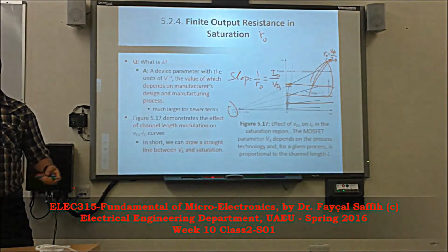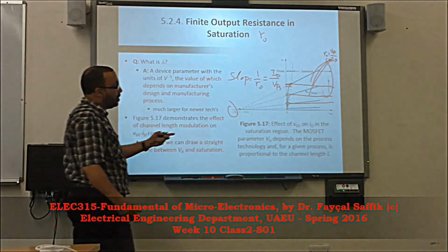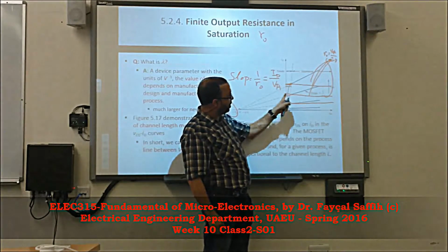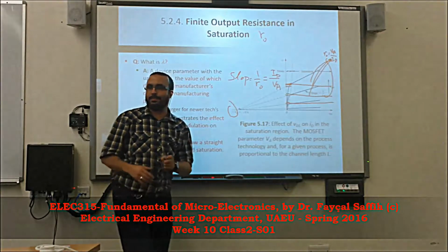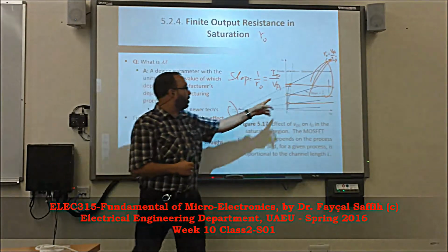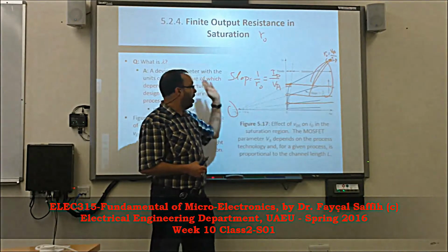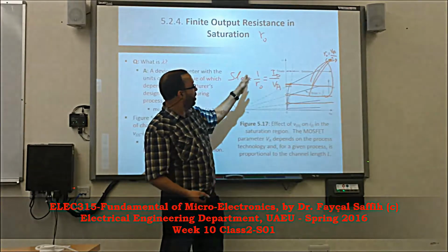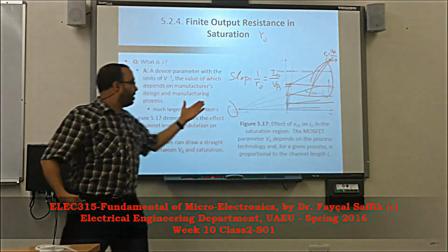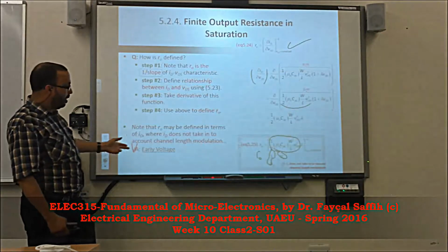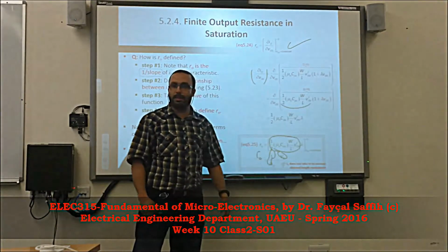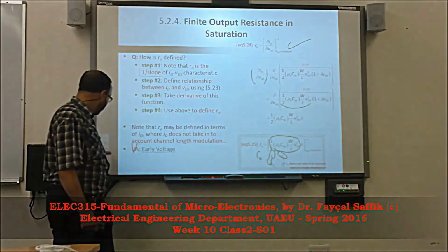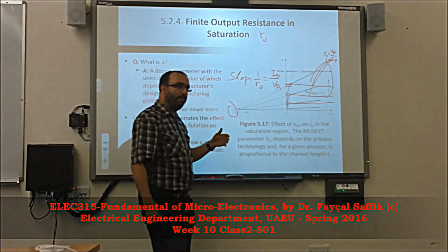That's it, you got it? As simple as that. But it is an approximation, not an exact value, you have to consider. It's a little bit up from the intersection here, tiny. That's why we use this value here. Then, bingo, ID divided by VA, so R0 is going to be VA/ID. That's exactly the same equation that we found here. Did you get that? VA/ID. He found it graphically and maybe with some theory.